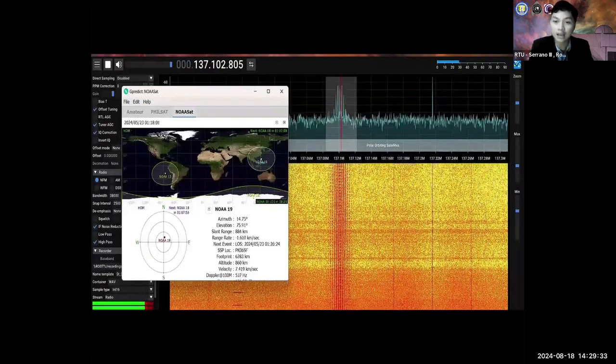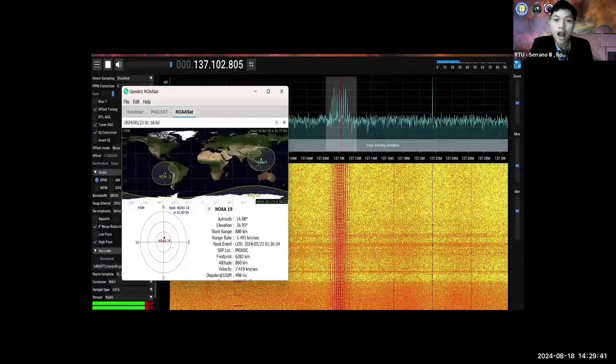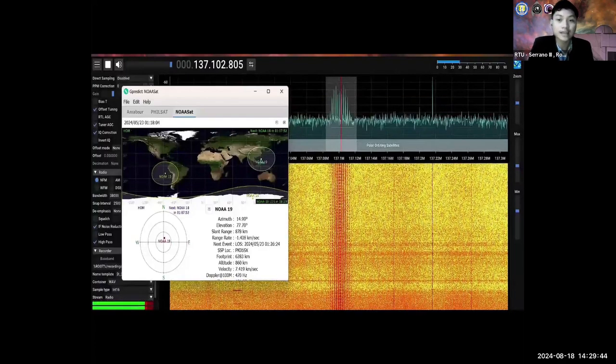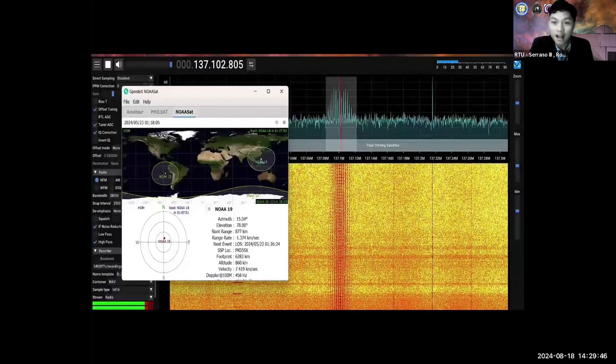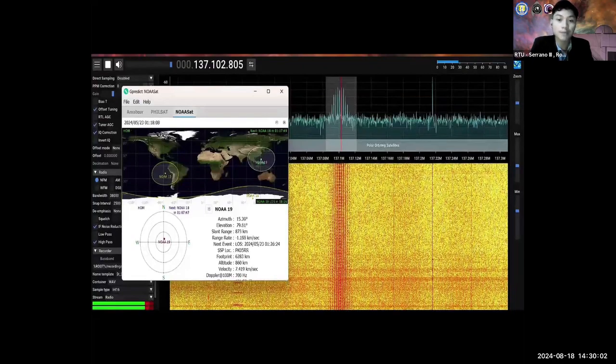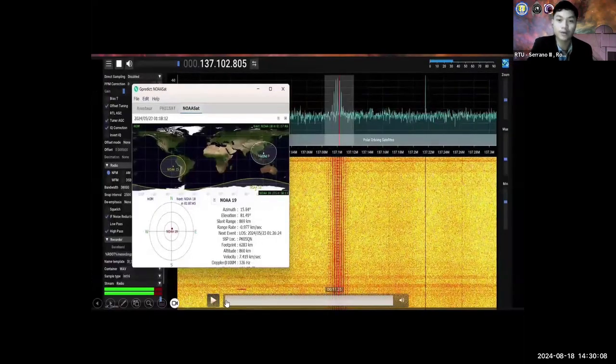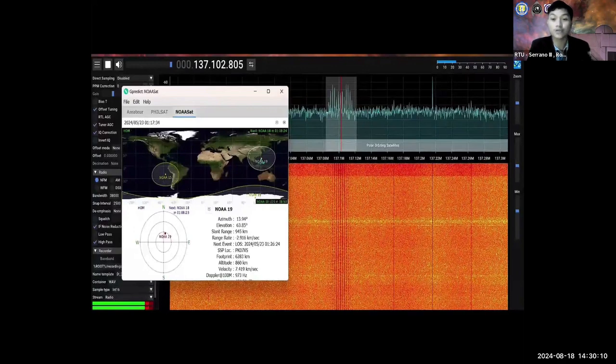Along with the tracking of the satellite, in the background you can see another software that we use, which is the SDR++. We use this software to receive, analyze, and process the APT signals that we receive from the NOAA-18 and the NOAA-19 satellites. As you can see in the background, the offset tuning, automatic gain control or AGC, and the IQ correction are selected in order to automatically adjust the gain of the incoming signal and to correct imperfections such as sudden frequency shifts or even inaccuracies.